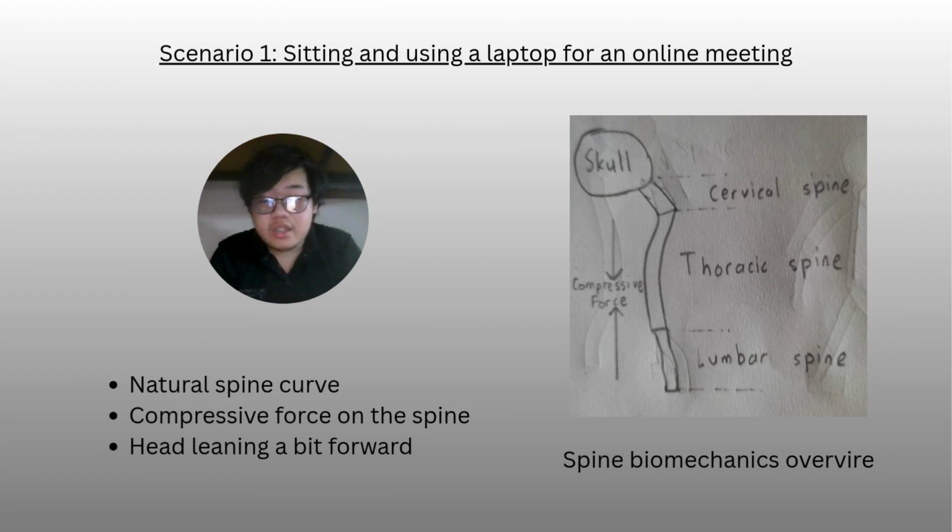The person's spine is in a position where it will be the most comfortable. The posture allows him to maintain the spine natural curve, while evenly distributing most of the body weight through the pelvis and the chair. Due to the person sitting on a chair, there are compressive forces acting on the spine from the body weight, and shear force on the lumbar spine from the head leaning forward. Speaking of which, the man's head is bent slightly downward, which would cause an increased moment acting on the neck.